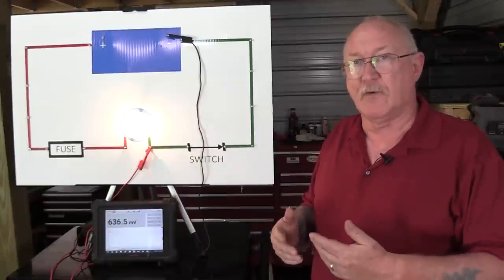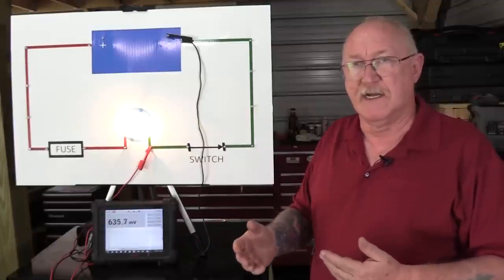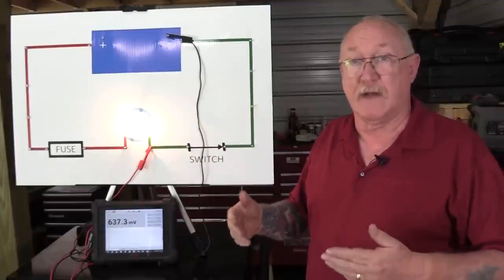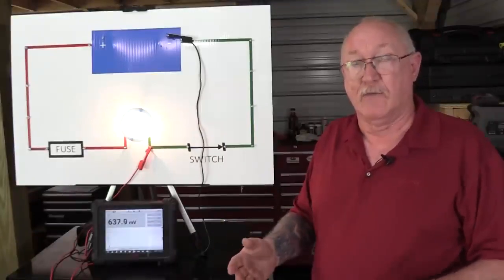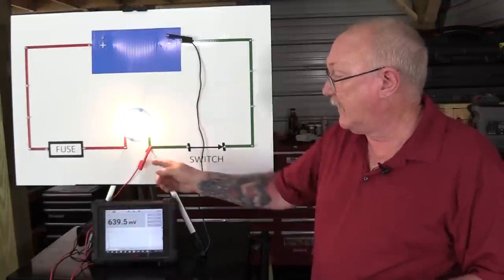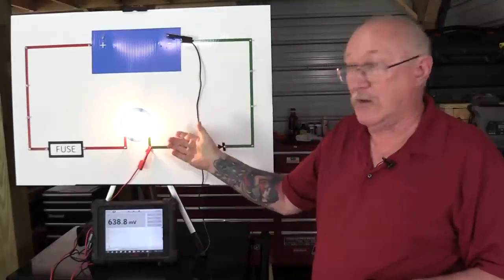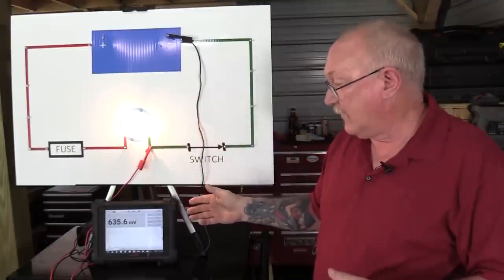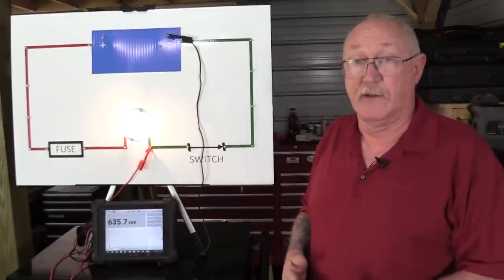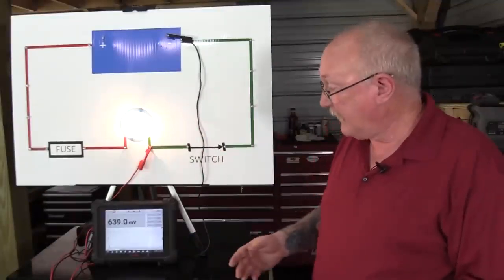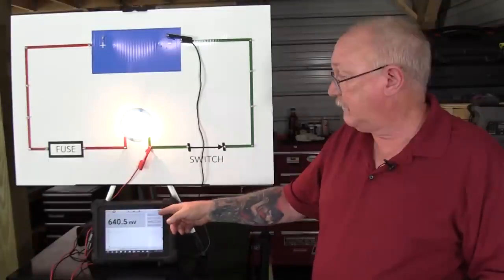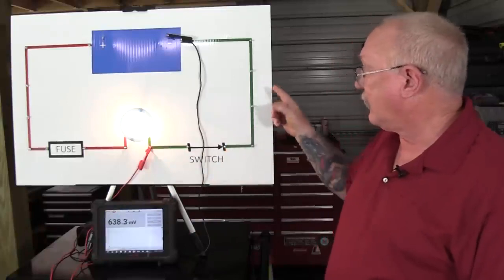Every time we use some voltage to get across a source of resistance, the difference between what went in and what's coming out is the amount of drop in that leg. Remember, voltage is measured between the meter leads, so in this case, from here to here, across that load, we lost over 10 volts from what we started with. That's a significant amount. But notice we still have some left. Well, why do we have some left? Because we still have little mouths to feed on our way back.